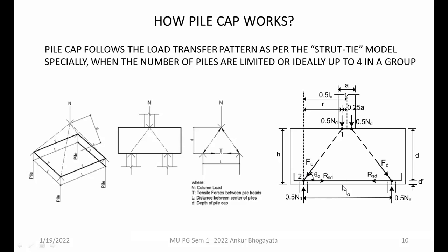Similarly, just below the base, where there is no compression is assumed. So in that case, the entire behavior of this portion will look like a beam, or ideally a deep beam. So there will be a fear of the flexure also sometimes if the spacing is too large between the given piles itself. So there is a complex behavior definitely of the pile cap, especially in case of more number of piles.